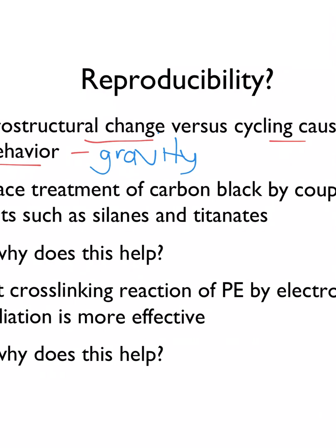It's kind of what you're saying, but the carbon's going to try to settle under that applied gravity. So you take carbon, you put it in a liquid, gravity's going to pull on it. Now this is polyethylene, it's not water, but even so, if there's enough gravity acting on it for a long enough time, or you're adding 9 times gravity acting on it for a long enough time, then it can start to pull that carbon black out of its original position, all right?